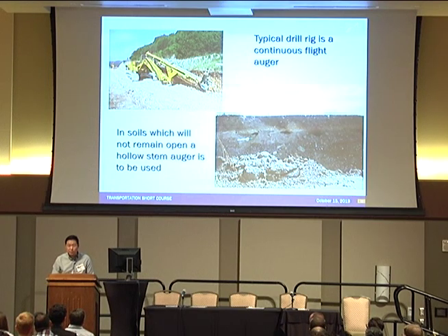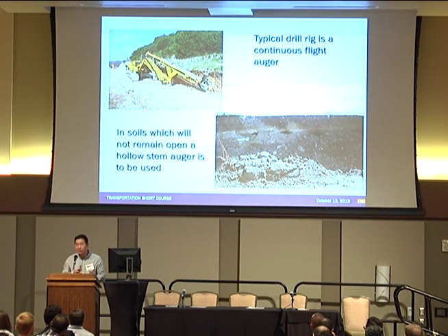The typical price for the hollow core bar is about 150% or 200%, because you are going to waste lots of grout during the installation. But if you see the site condition or soil condition during the design, you need to consider adding a note on the requirement for a cased hole or the hollow core bar, so you avoid any conflict like a change order.